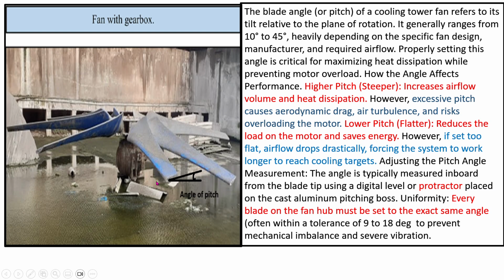Normally, during hot weather, much more cooling air flow is required. At that time we increase the angle, and in the winter season, there is no need for so much air flow. At that time we reduce the angle, and like this we are saving some energy.